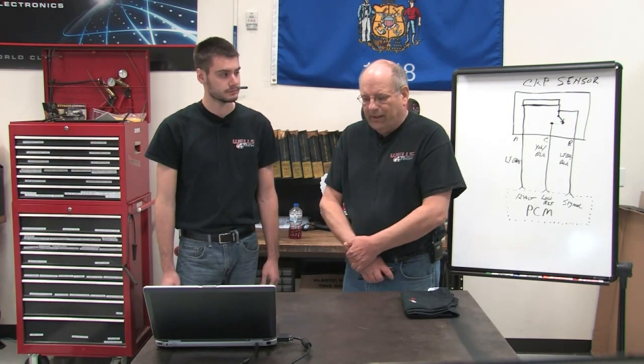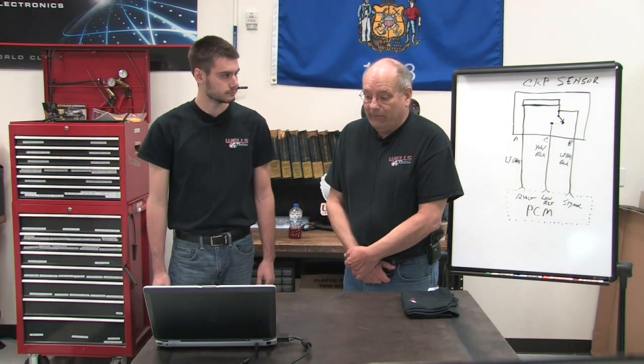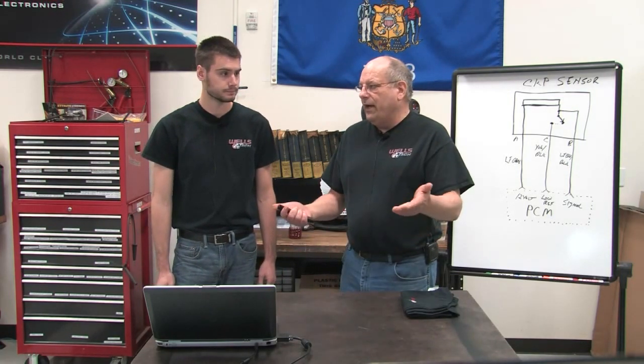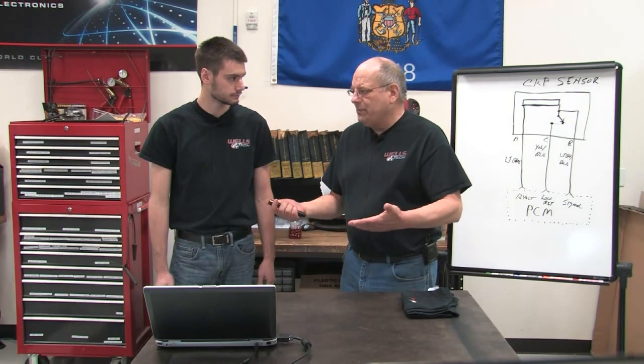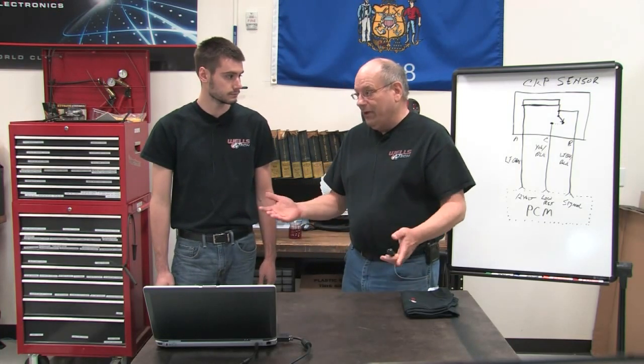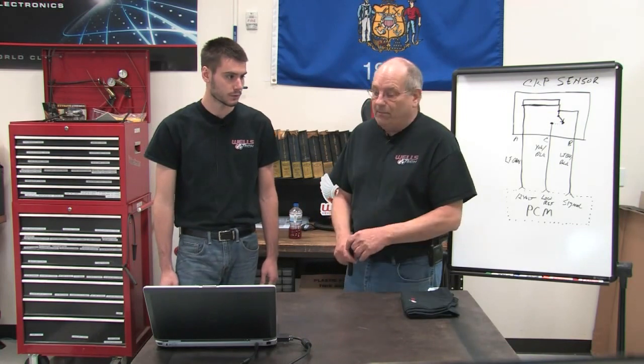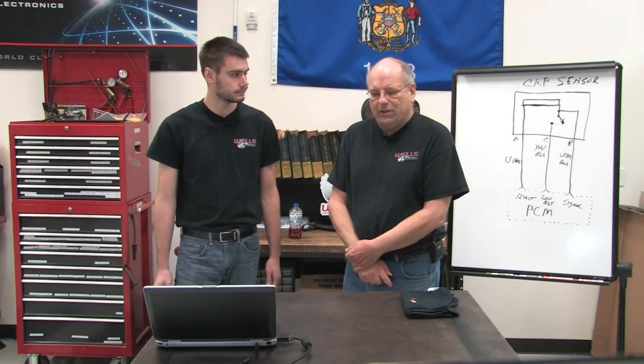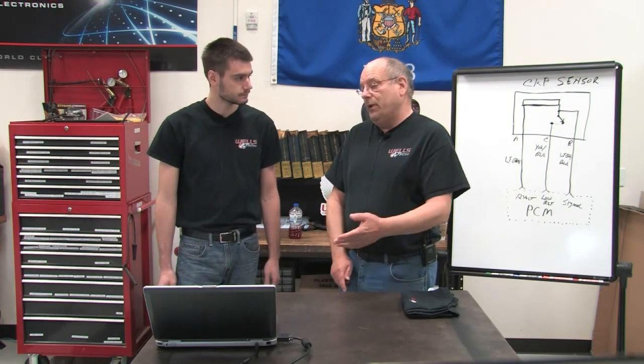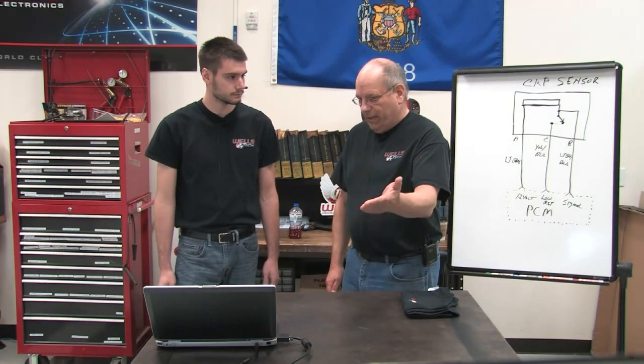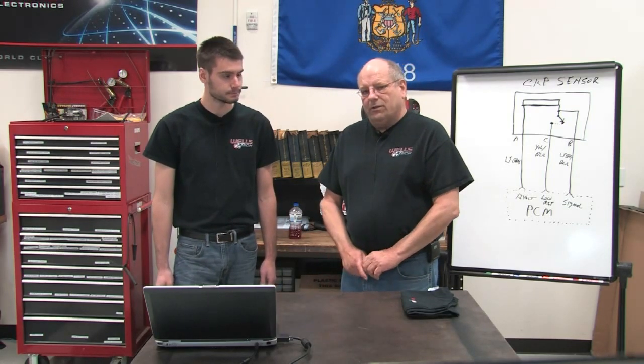Just very interesting, and not a lot of information on it. It is very interesting. And when you do run into an anomaly like that, it can be very confusing. For guys in the shop, are they going to spend that extra time? The vehicle's running good, the check engine light hasn't come back on, everything's back. Or would they have put a PCM in here? I was ready to condemn the PCM. I was too. Would they just throw a PCM in, thinking that because of the shorted wires, that's what ruined the PCM? So be careful.